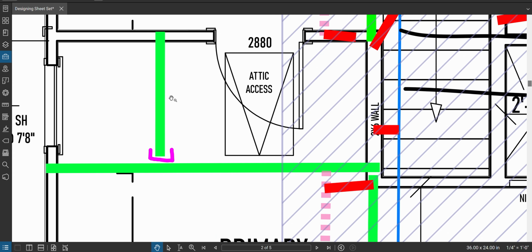Okay. Top edge, bottom edge. What I'm going to do is I'm going to go end supports only for a lot of these beams, because I don't want to have to think about it. And this is being conservative, and it's faster. And it really doesn't matter for short beams that are not huge. Okay. Loads. All right. Let me hide this guy. So I have ceiling and I have roof. So I'm going to go back to my drawing, and I'm going to say, what is the tributary width of the ceiling I'm responsible for? Halfway there to there. Halfway from here to the wall where the ceiling is held up. 5 feet. Great. So I will say 5 feet on top.